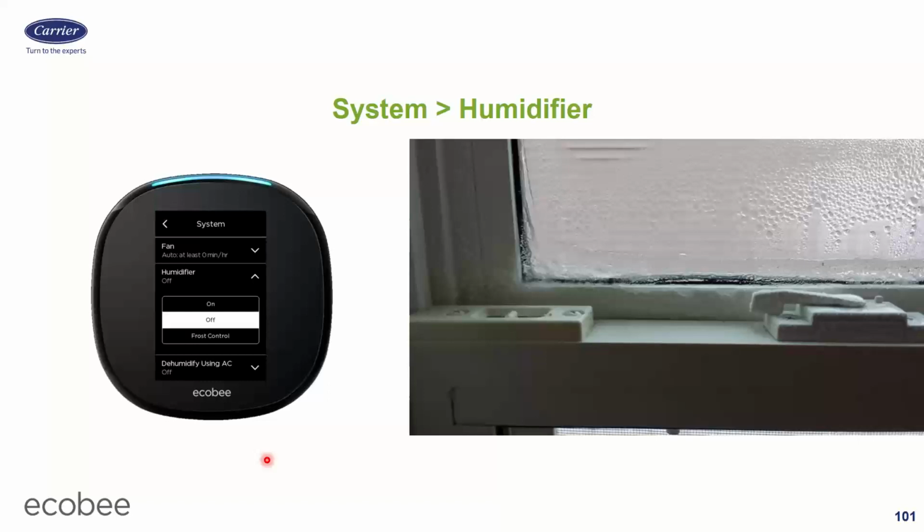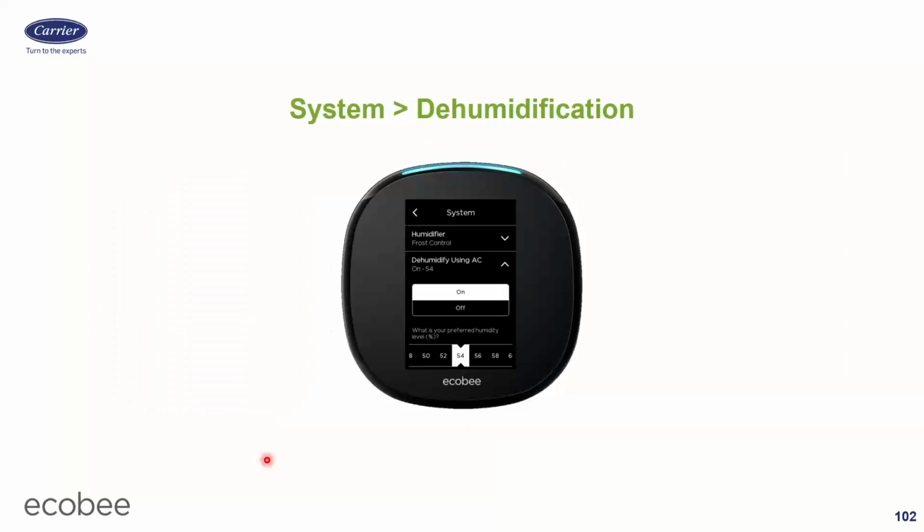Below the humidifier section is the humidity section. So even though I don't have a humidifier in this example, if I did, I'd have to configure a dehumidification set point for that. But in this case, I don't have a dehumidifier because I wired up a humidifier. And remember, the Ecobee 5 can only do one or the other. But I did tell it I wanted to do the AC overcool max. And I told it 3 degrees max, if you recall from last week.